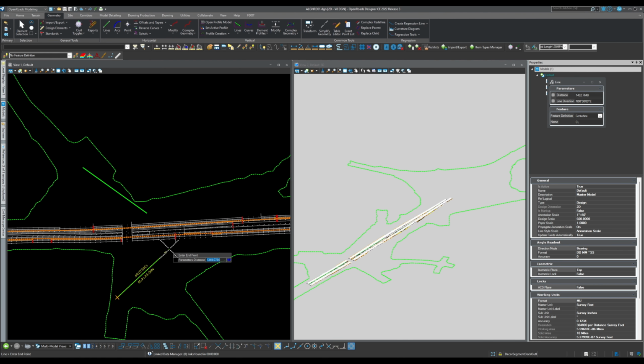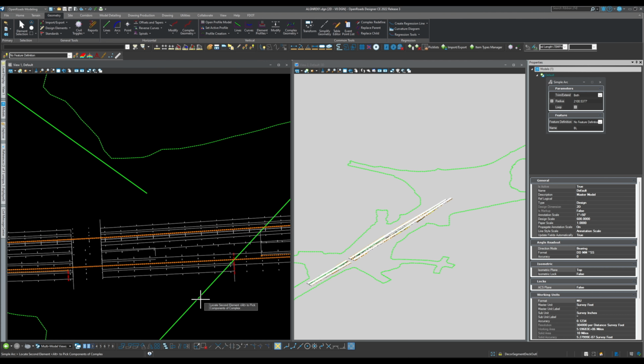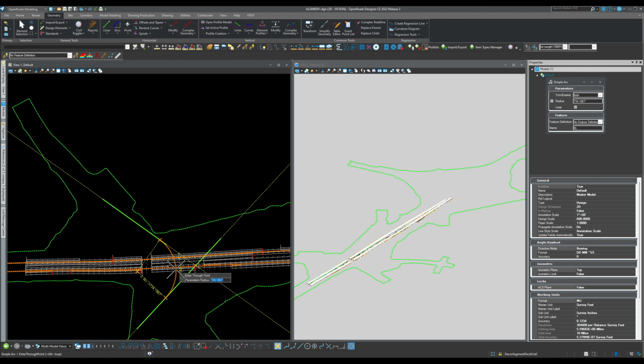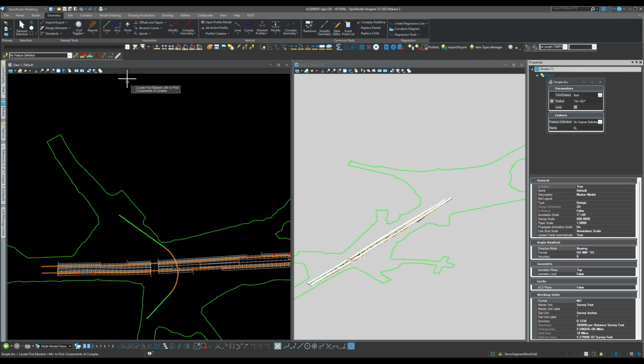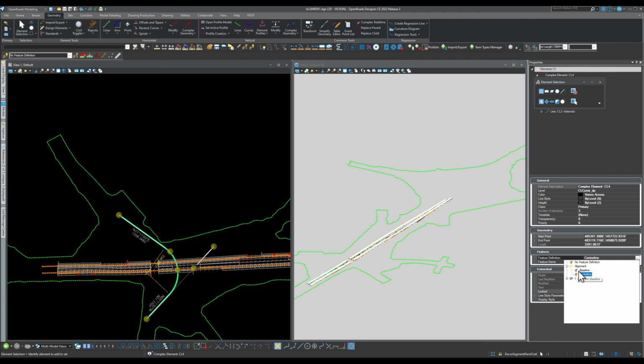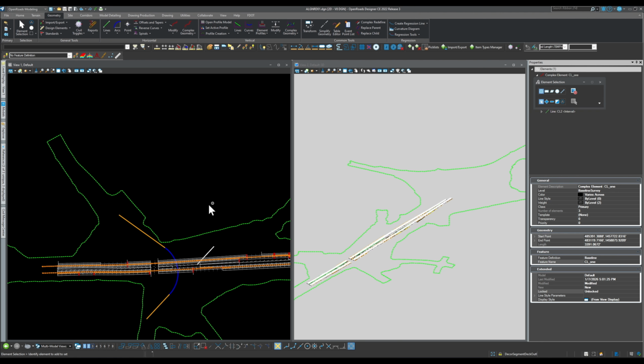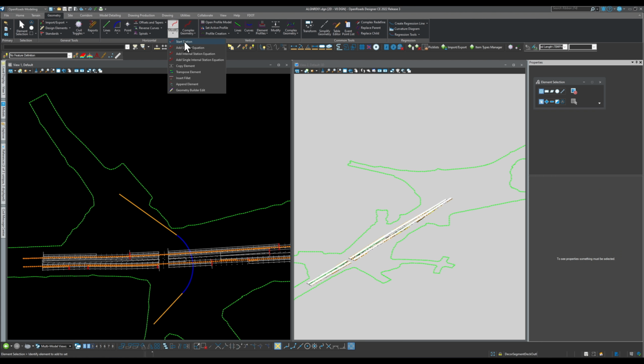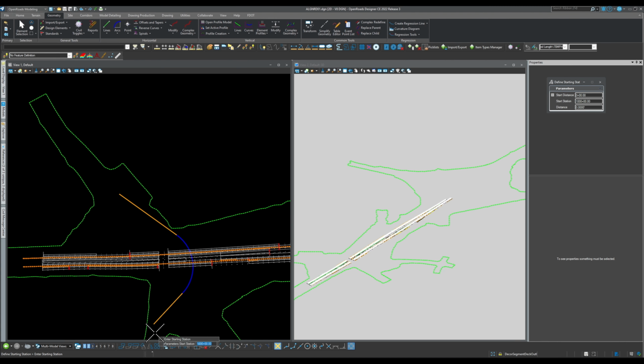And then just imagine it is going like this, but then I'm going to make some curves between them. Or just one. Okay. And then I want to complex it. Make sure there's going to be a baseline since it's proposed. And then let's call this one CL1. Okay. Let's also add stations to it. Say start from here, 1,000. Good.